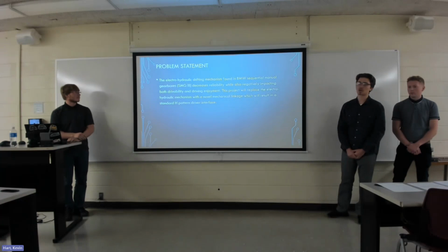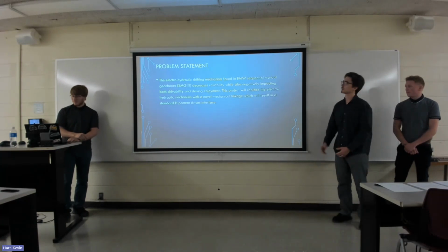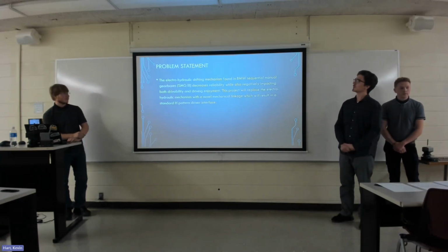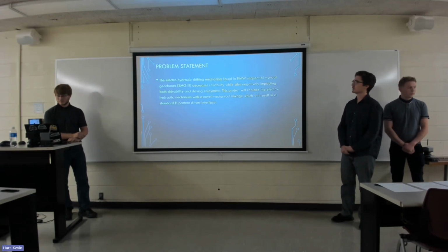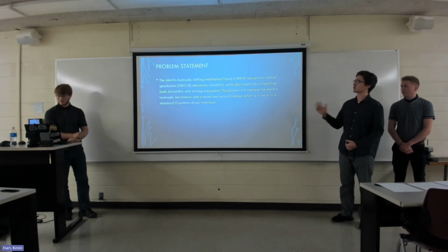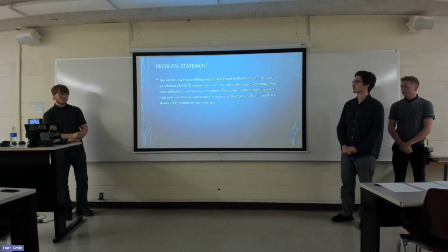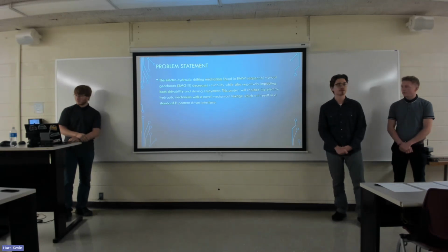Yes, so this leads to our problem statement. The electrohydraulic shifting mechanism found in the BMW is known to decrease the reliability while also negatively impacting the drivability and driving enjoyment. So our project statement is it will replace the electrohydraulic mechanism with a novel mechanical linkage, which will result in a standard H-pattern driver interface.